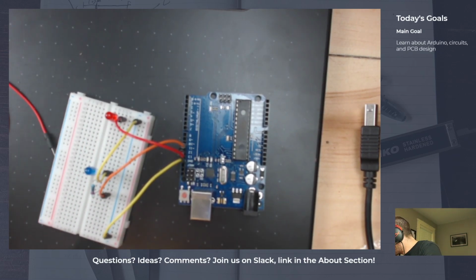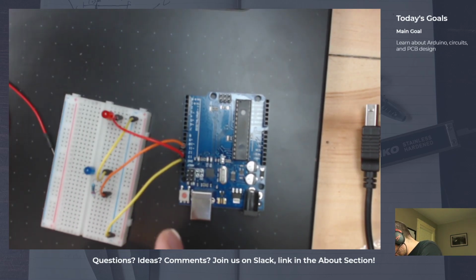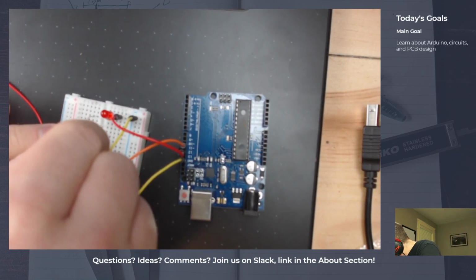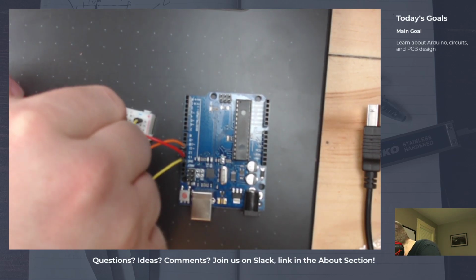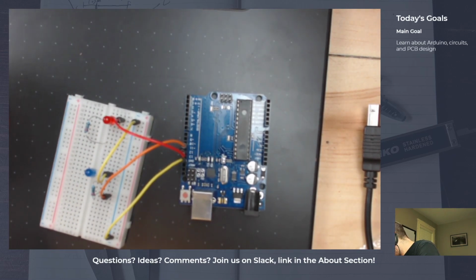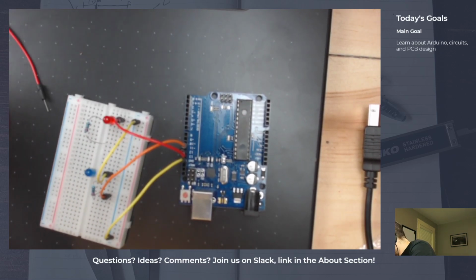All right, so let's finish wiring this up. We had run the red wire to the positive side of the LED, and then we'll want to run a resistor through from the other side of the LED. So we got that connected there, and then we'll want to run one more yellow wire to ground, and then our circuit should be complete.